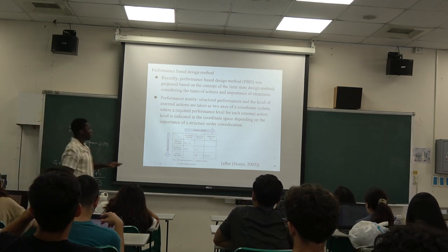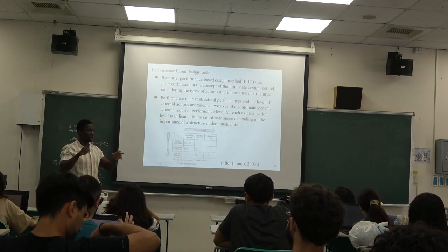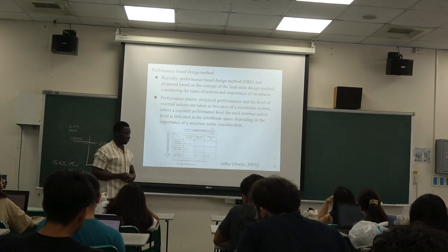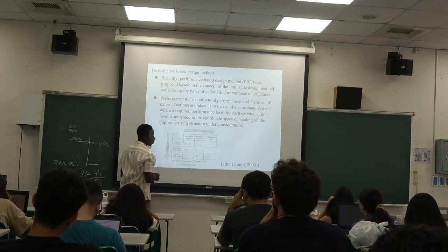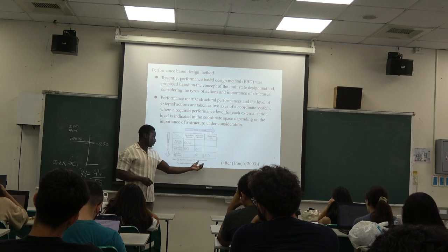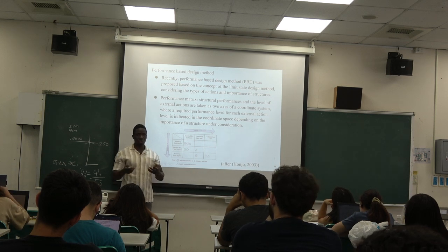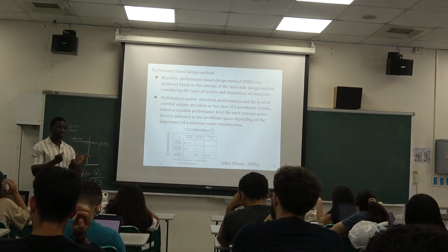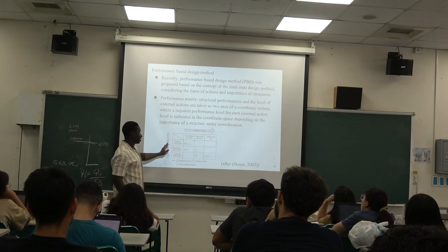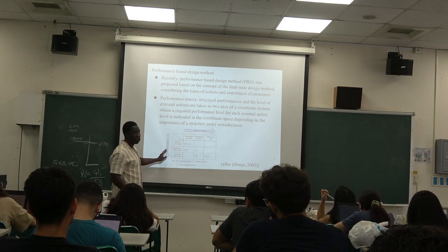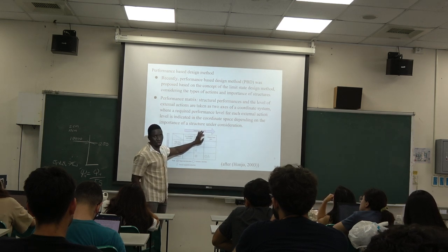Okay, so if we look here, it can actually give us a much better idea of this concept, the limit state design concept. So for example here, you have a very important structure. Here, you have an ordinary structure. And this represents an easily repairable structure. The structures that are not very important, but they're also very easy to repair. So here we have the magnitude of actions. That is how frequent this happens, or what impact we might observe, and what kind of damage or risk are we willing to take.